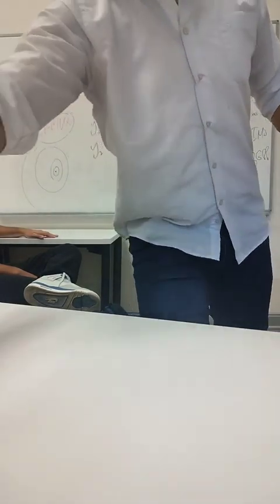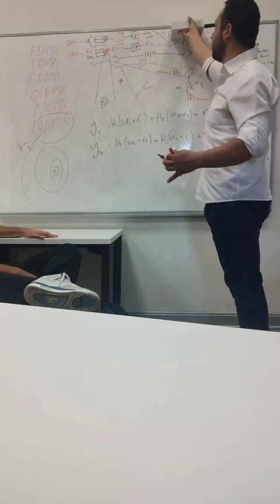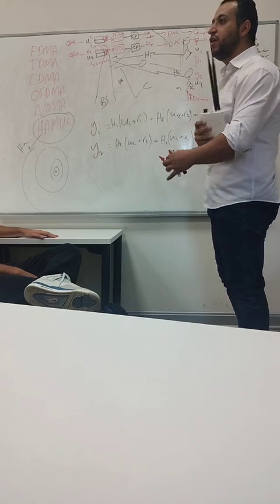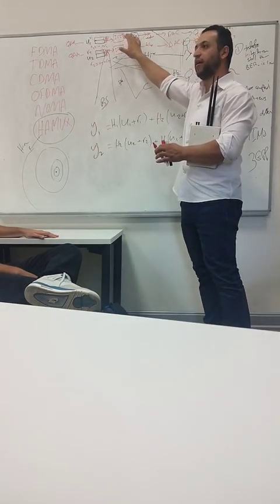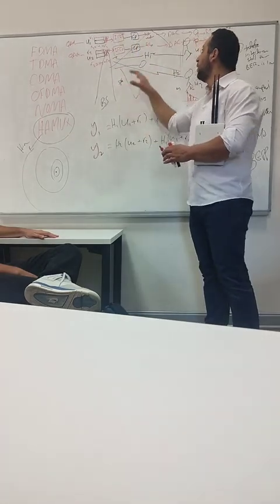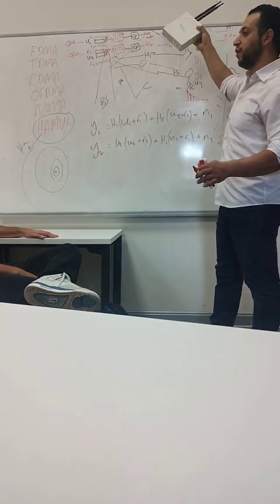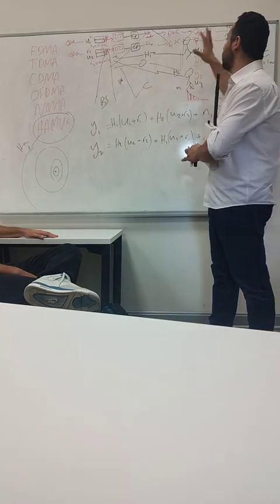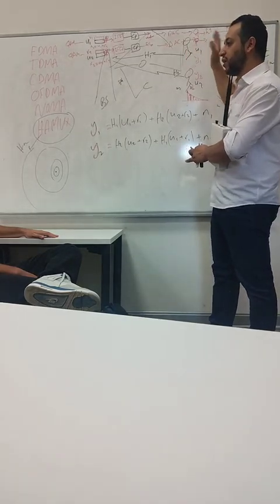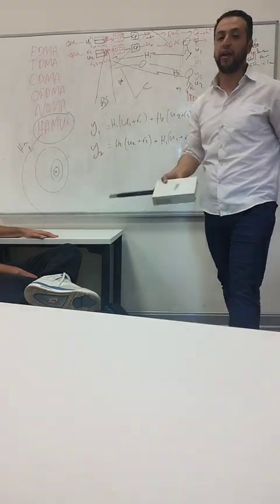And then you pass it through the digital to analog converter. Once we reach the digital to analog converter, we said that this is done in the PC or any computing device like a Raspberry Pi. And after that, you do this on the radio. This is the radio that takes the signal, with the oscillator, digital to analog converter, and analog to digital converter, and then transmits your signal from the antenna.